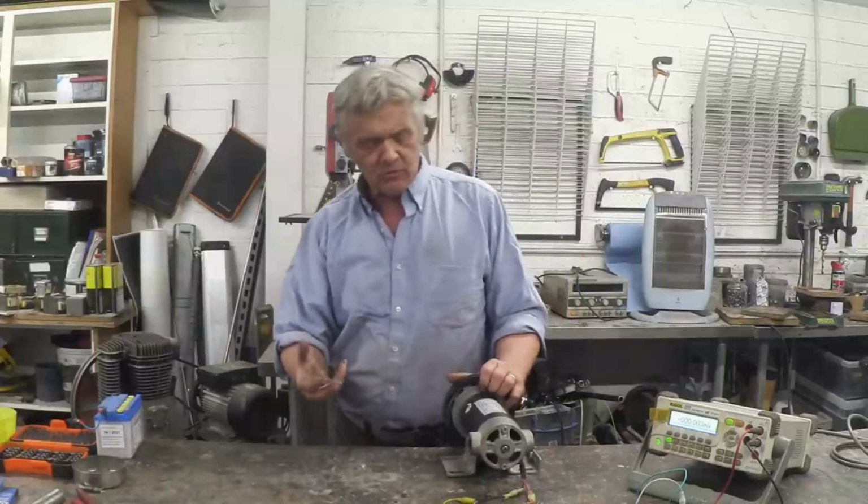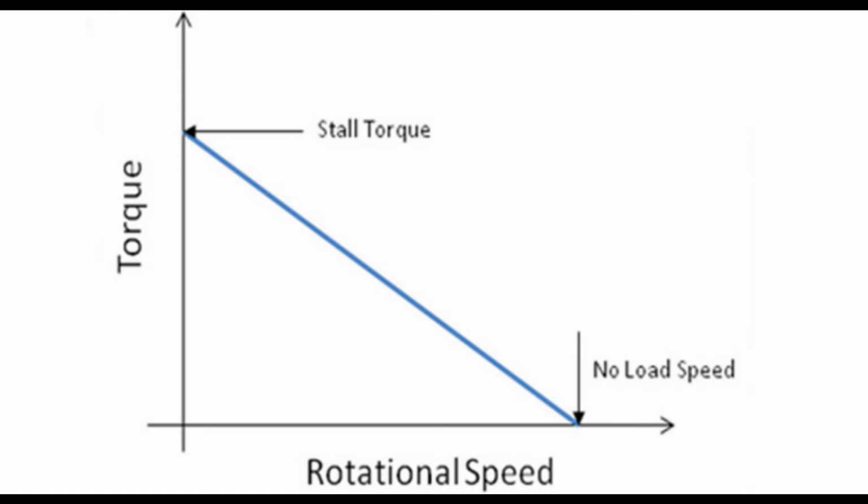I also think it's very interesting, but of course it begs the question, what use is it? Most generation applications actually turn relatively slowly, far less than 1000 RPM. Most motors turn much quicker than that, sort of the 2.5, 3000 RPM range, and so there's a mismatch very often. Now you can correct that mismatch by using gearing, which is exactly what we did. And the same ideas are going to apply with gearing in terms of the ratio of the speed to the torque that you're going to suffer when it comes to running up a few gears.